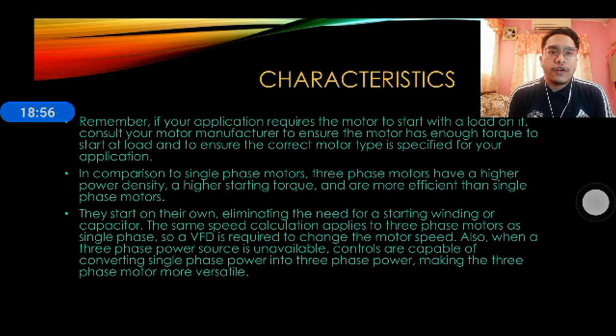But remember, if your application requires the motor to start with a load, consult your motor manufacturer to ensure that the motor has enough torque to start at the load, and ensure the correct motor type is specified for your application. In comparison to single phase motor, three phase motor has a higher power density, of course, and a higher starting torque, and also is more efficient than single phase motor. They start on their own, eliminating the need for starting windings or capacitor.